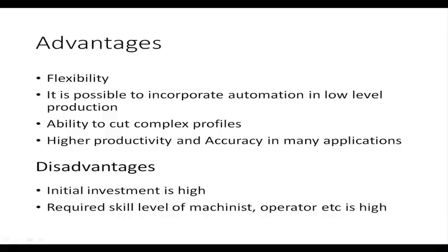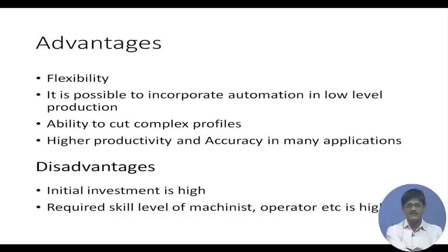So, finally, let us look at the advantages of CNC machines. It is more flexible, it is possible to incorporate automation in low level production, we have the ability to cut complex profiles, and in many applications we can attain higher productivity and accuracy. The disadvantage is that the initial investment is very high and the required skill level of the machinist, operator, etc. is high.